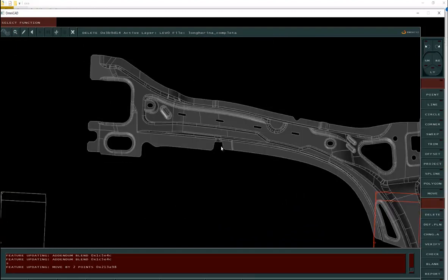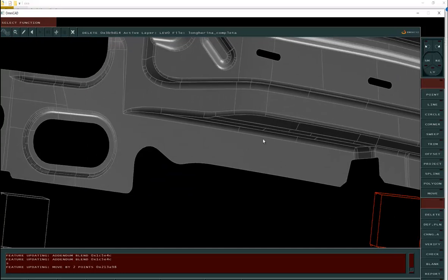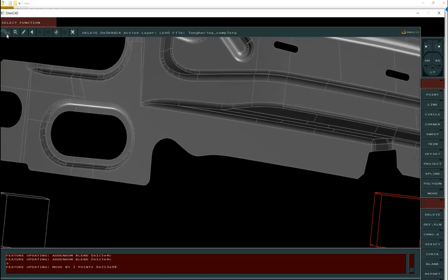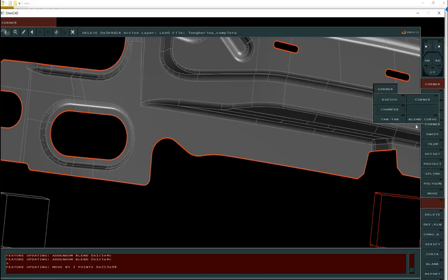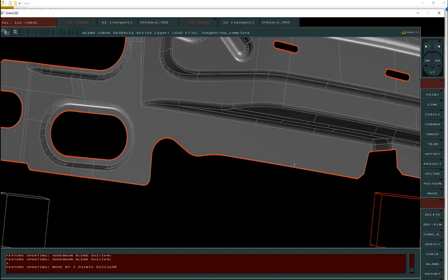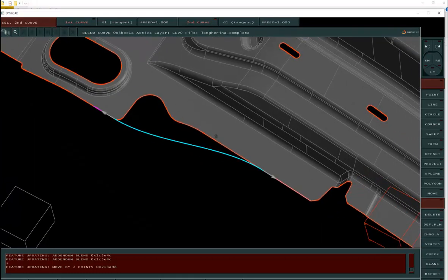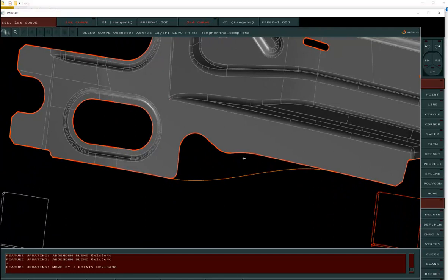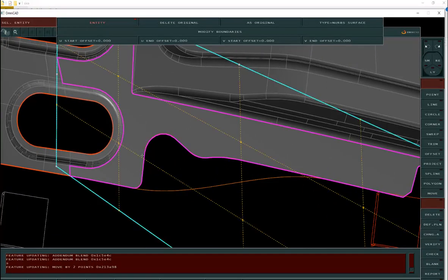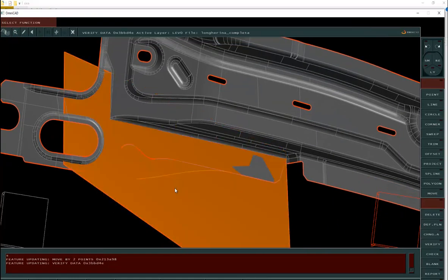with the strange profile like this one or this other one, and we open the topology and use a simple curve. Bend the curve, select from this curve and this other curve, and you set from this direction I want to have this profile. Here I will decide information of the surface, keep origin as active, and I will cut and trim the rest